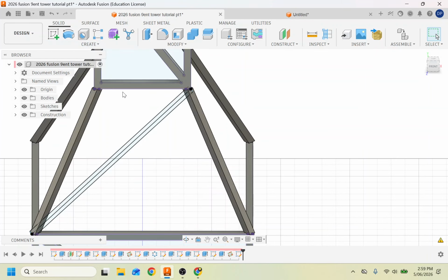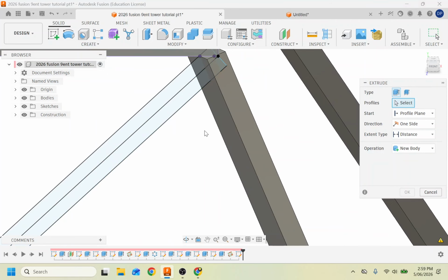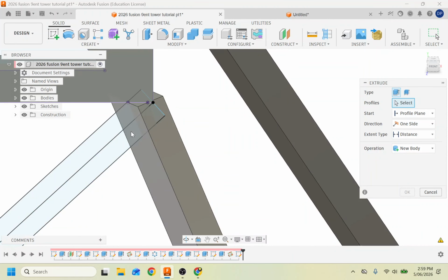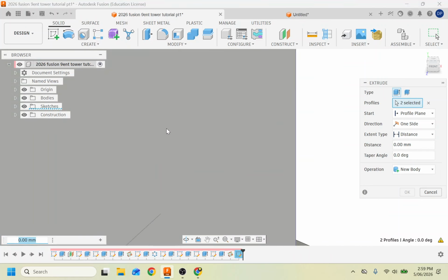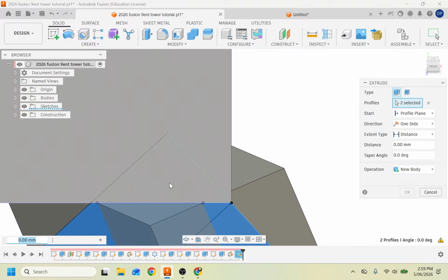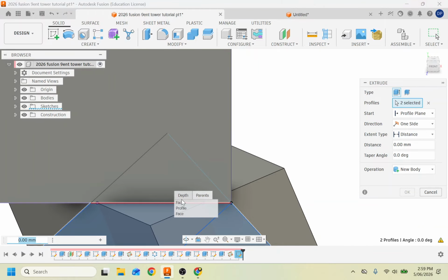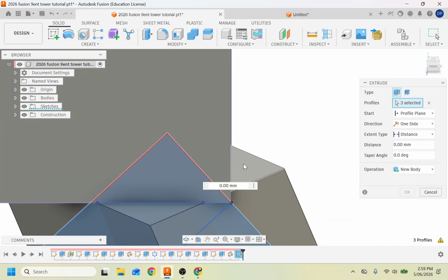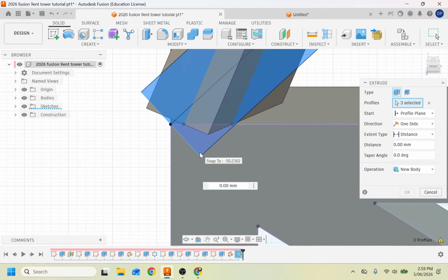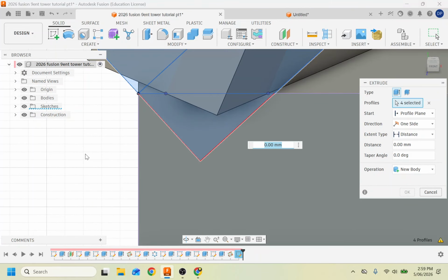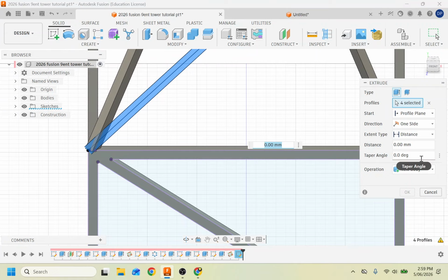We will then extrude this. And now when we extrude it, we've got to make sure that we select everything. Because as we select this and this, see how we're missing this part up here? This part's not selected. So I hold down the mouse and make sure that blue part is selected over there. And I think the same at the bottom, down here. Yep, this isn't selected, so I select that now. So now it's all done.